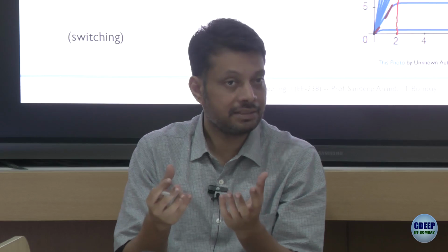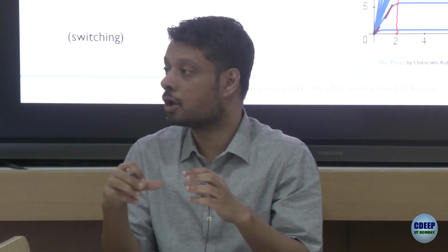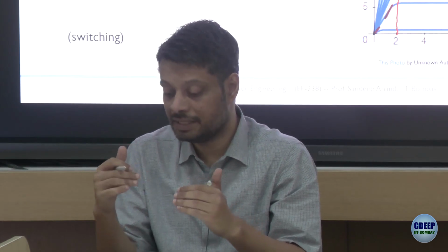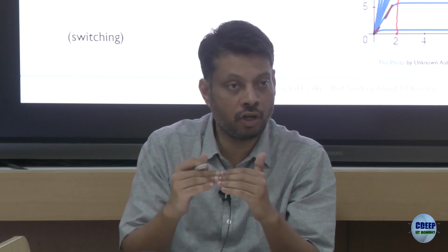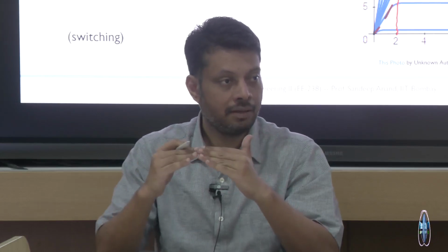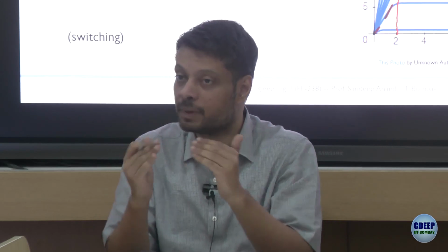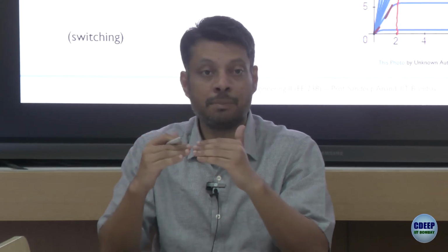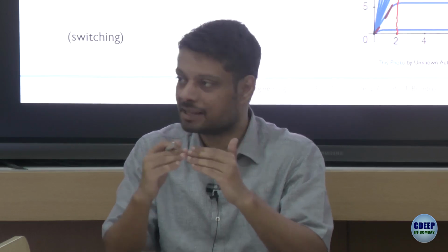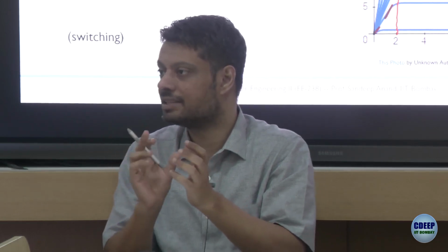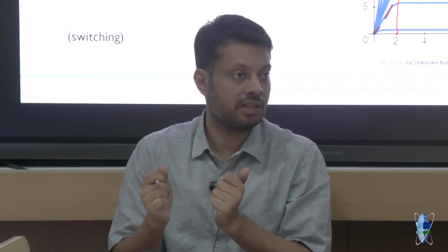It's the same device more or less, but the operating point is different. Now we operate at cutoff or in the ohmic region, that means the switch is on or off, with nothing in between. But as a linear regulator, we operate in between, because we want it to mimic a resistance or a current source. They are neither completely on nor completely off, so they have a large voltage drop and also allow current to flow simultaneously.